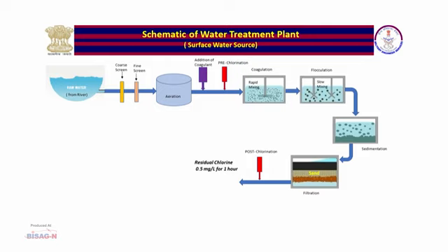When it comes to application of chlorine, it can be done by 3 methods. First is addition of weak solution prepared from bleaching powder. Second is addition of weak solution of chlorine prepared by electrolyzing a solution of brine. And third method is by addition of chlorine either in gaseous form or in form of solution made by dissolving gaseous chlorine in small auxiliary flow of water.